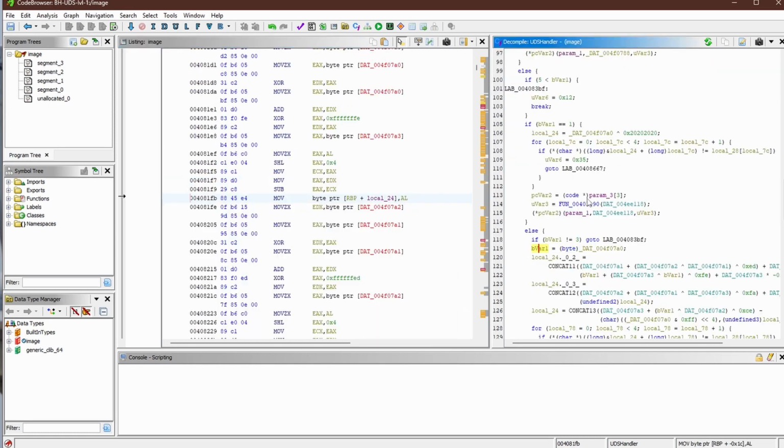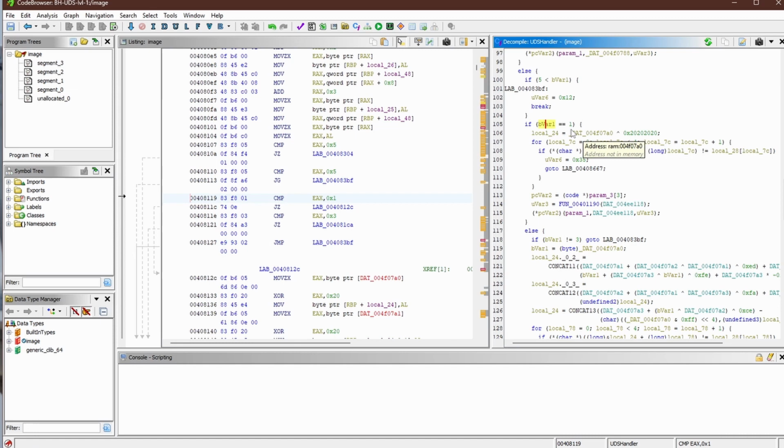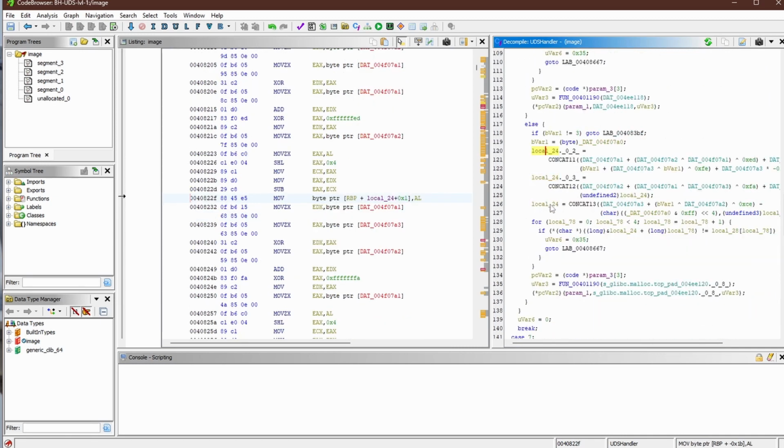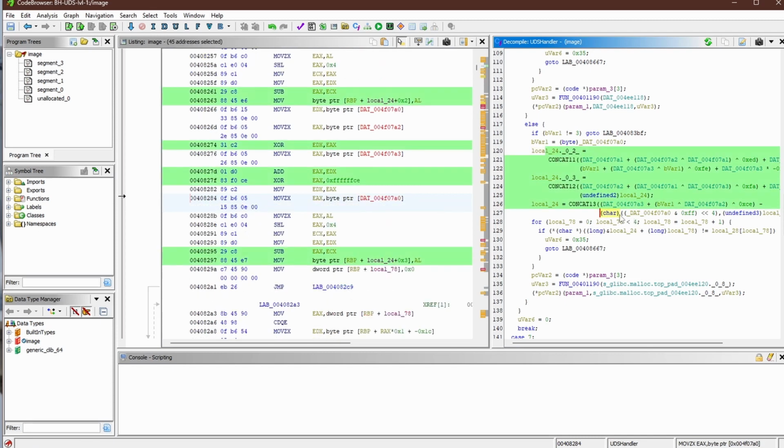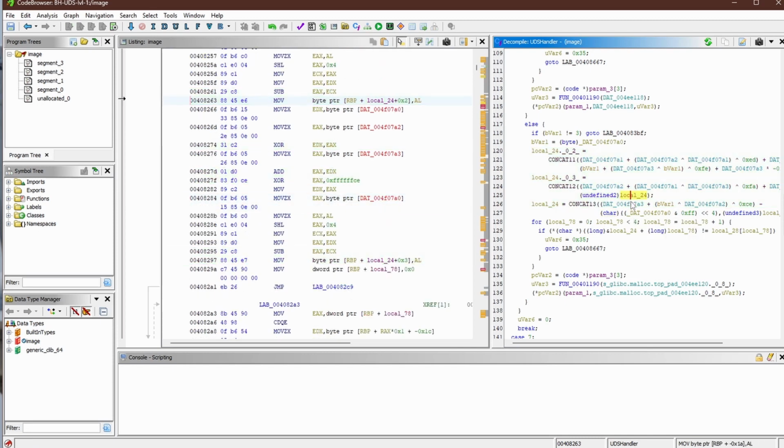Going back to the code, let's look at the initial if and see what it's checking for. Presuming that this if is checking for level 1 and level 3, we can safely assume that bvar1 here is checking for a subfunction value for level 1, followed by an else case checking for level 3, which means that the following section of code that spans between lines 120 through 127 is the key generation code that will take the seed and create the key.